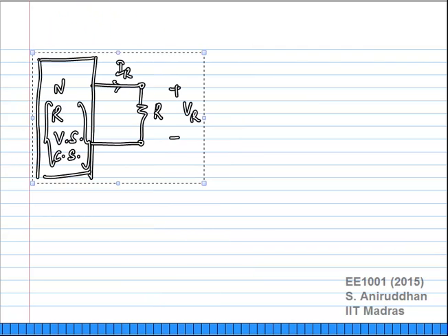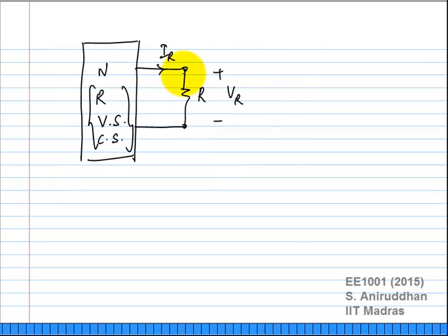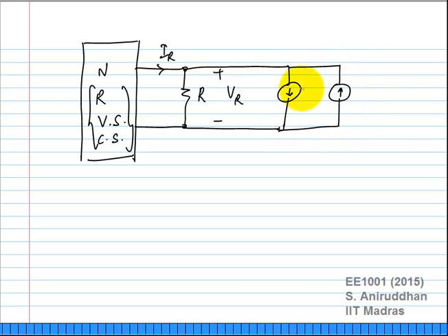Then what we said, we'll take this, and if you actually go ahead and connect these back-to-back current sources here, so I am going to use back-to-back current sources of value IR. What is the current here? 0, correct? We just said that. So the current through these wires is going to be 0. Next step, I am just going to redraw this network slightly differently. These are all ideal wires.